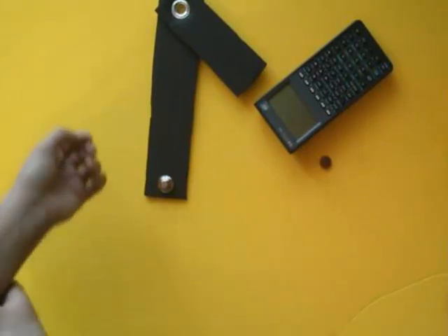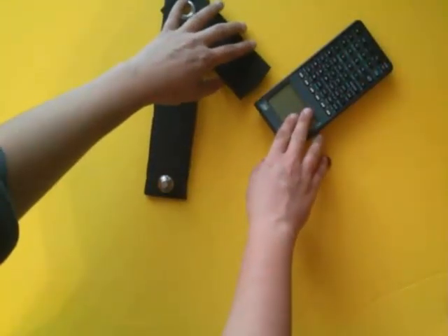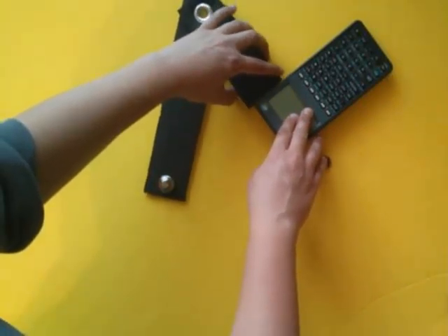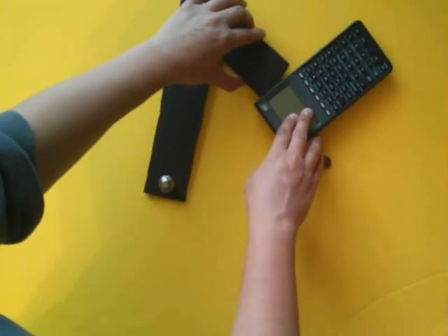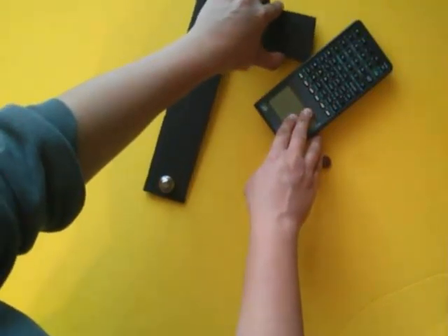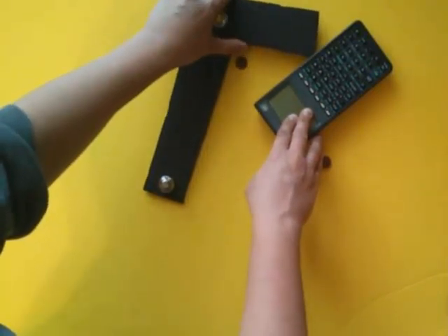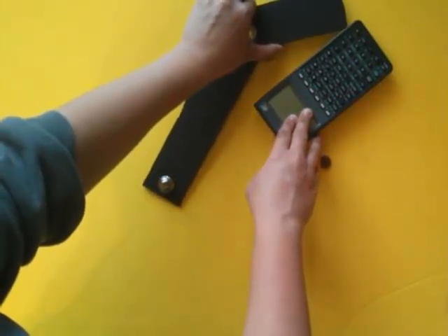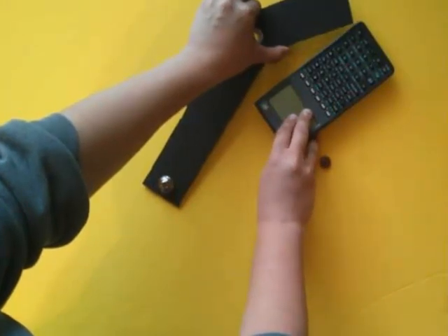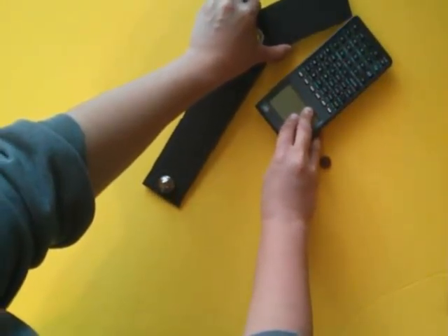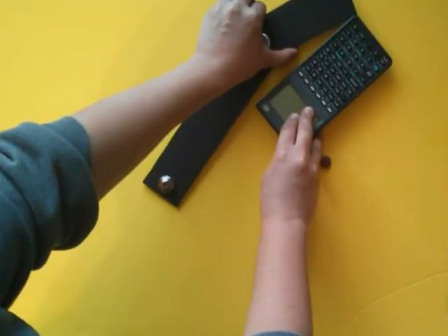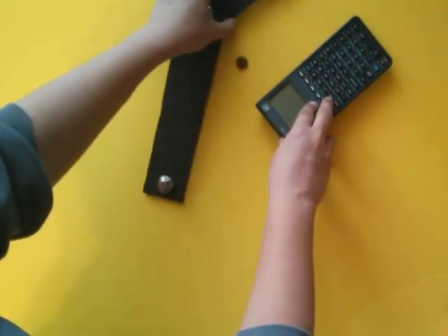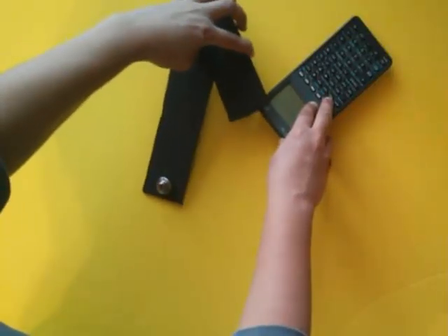actual collisions. The way we do that is by placing the end effector at each of the points along the outside of the object that is the obstacle. And for each of these points where the end effector collides with a point on the perimeter of the obstacle, I'll plot those theta 1 and theta 2 points in my configuration space.